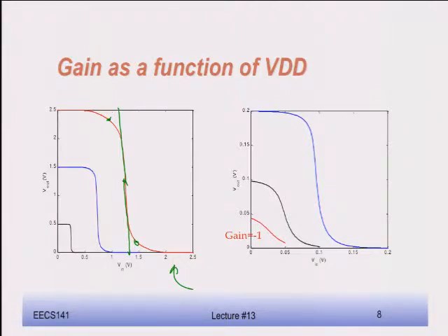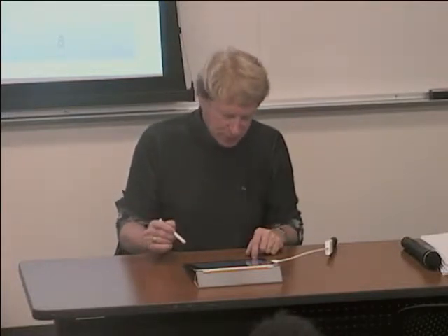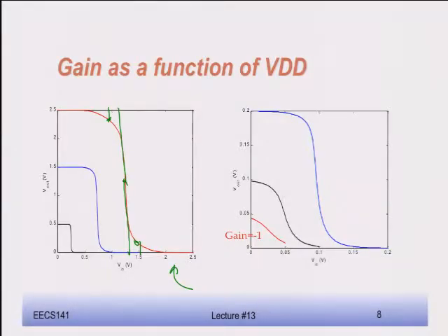So you can see that in this case, when the gain is really high, I might have somewhat of an optimistic view on my noise margins, because in reality, my noise margins are a little bit smaller here. So it's somewhat of an optimistic approximation. But you will see that if you go to lower and lower values of the voltage, the approximation is pretty good.